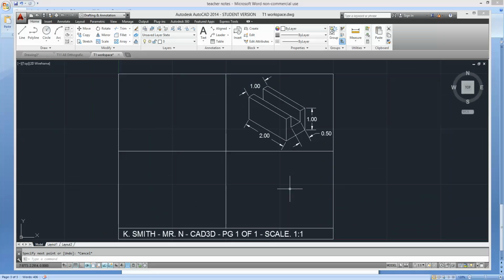We are going to set up our workspace in these four different sections. This is going to help us provide a nice clean piece of paper when we're drawing our orthographic views. On the bottom left corner is going to be presented our front view. The bottom right corner is going to be our side view, and our top left corner is going to be the top view. The first thing that we're going to do is look at our isometric drawing and try to recreate this front view.